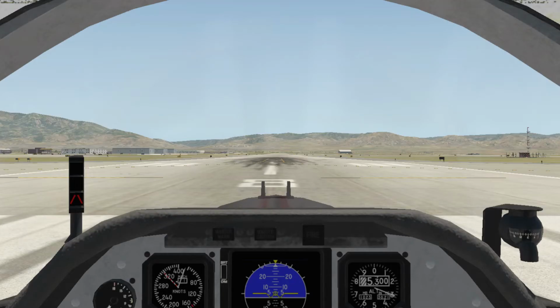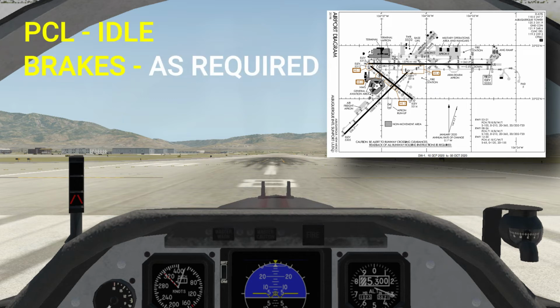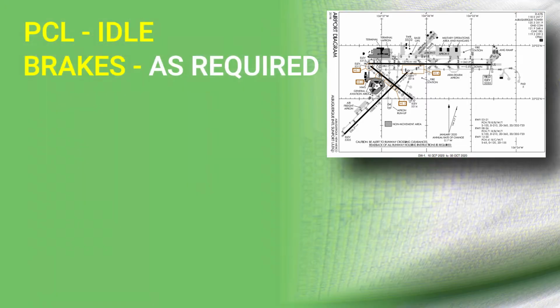That said, if you experience an engine failure immediately after takeoff, you'd still have quite a bit of runway to aerobrake until below 102 knots maximum braking speed. If you abort above maximum braking speed, select idle but do not apply the brakes until at or below max braking speed if runway length permits.